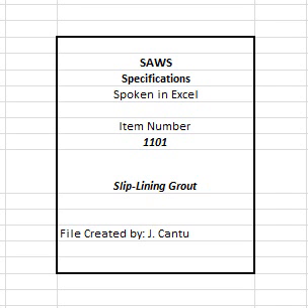4. Limit pressure on the annular space to prevent damage to the liner, do not exceed 5 psi. Regardless of the pressure, contractor shall be solely responsible for any damage or distortion to slip liner pipe due to grouting. At the bulkhead opposite to the point of grouting, provide and monitor an open-ended high point tap or equivalent vent. 5. Pump grout until grout within 0.3 pounds per gallon of specified grout injection density discharges from the end opposite the injection point.